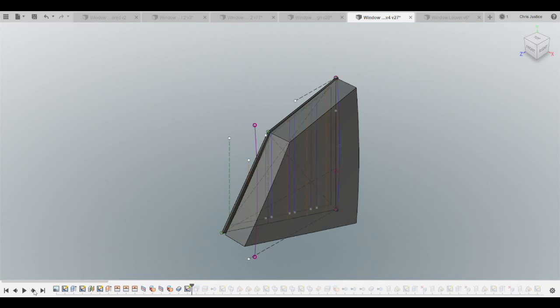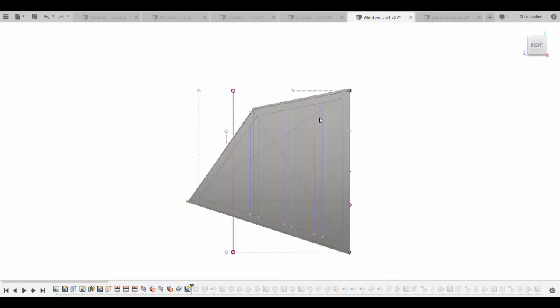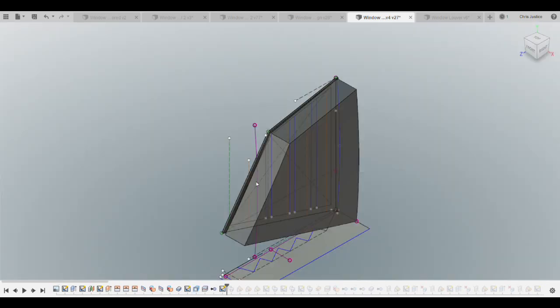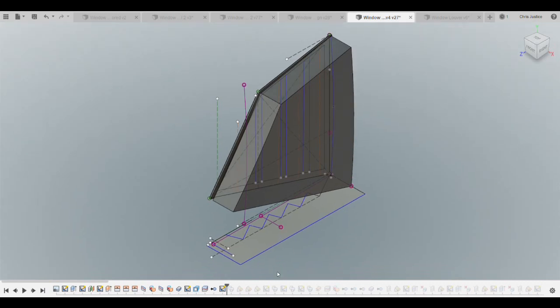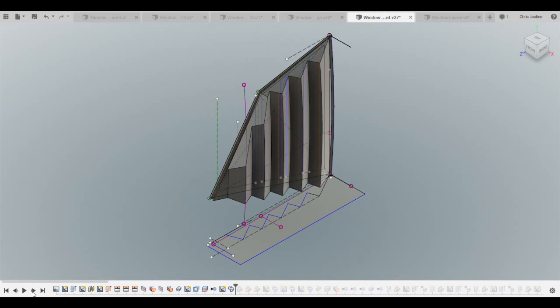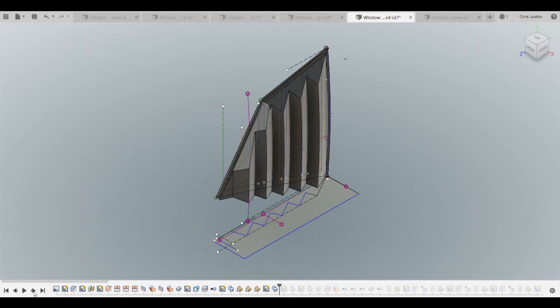The fins of the louver would need to be spaced correctly for my model, so I created a sketch on the original base plane to act as a guide for the fin extrusion sketch. I drew a sketch of the fin positions and extruded them using the curved construction line as a guide. I put taper on the top and bottom of the louvers to give an aerodynamic, aesthetic look to the louver.